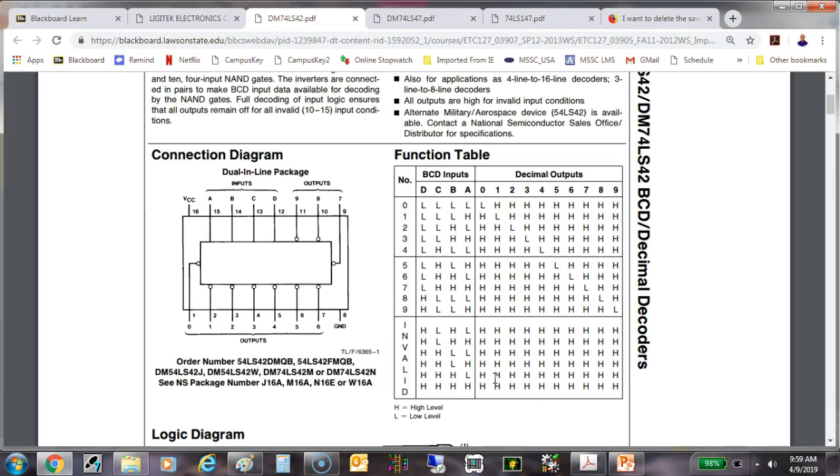Of course, now we know the difference. The one without the center letters, these are what we call the standard series. These are the first TTL gates that actually came out. And then they came out with other versions that vary the speed and the power characteristics. The LS series has lower power characteristics than the standard series, but it operates at the same speed.